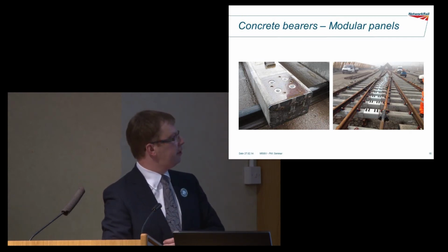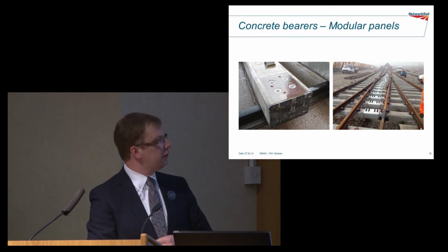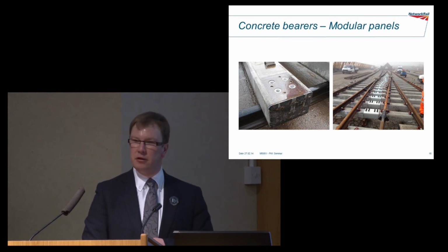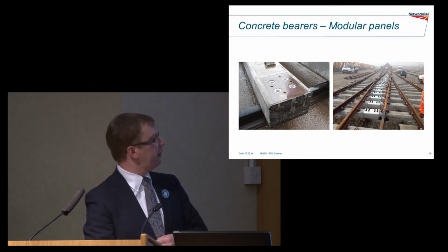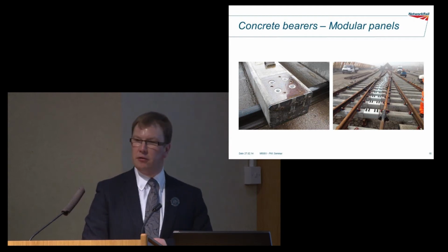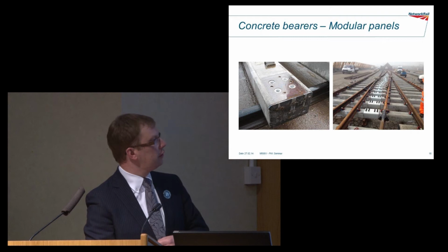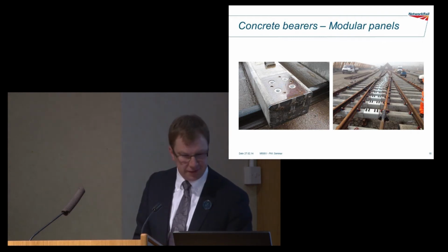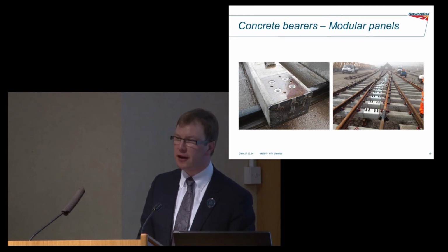Just for information, this is the bit that you don't normally see. So underneath here, this is a shear plate that's applied to the end of the bearer. And this does a number of things, but basically it ensures that we've got good strength around these holes on there. So that's something we don't often see unless you're involved with the actual construction.